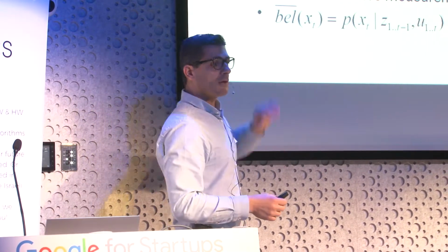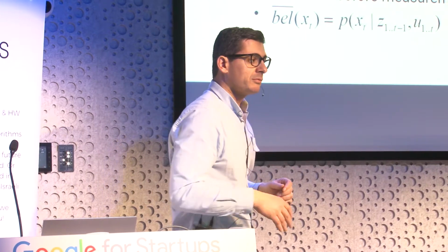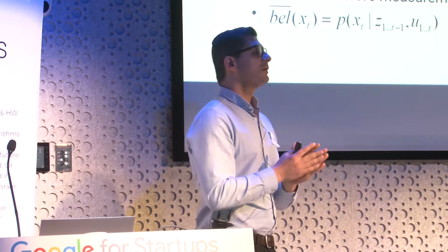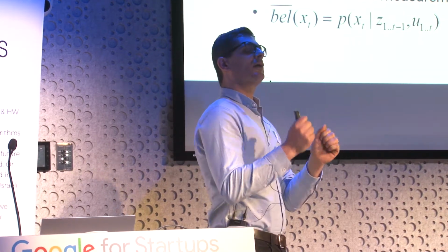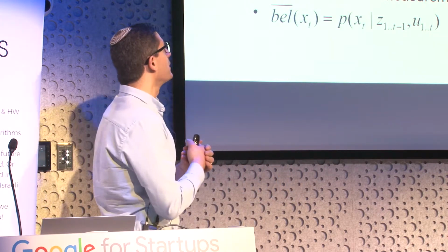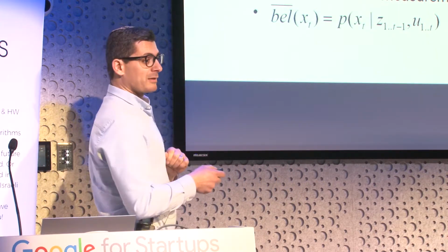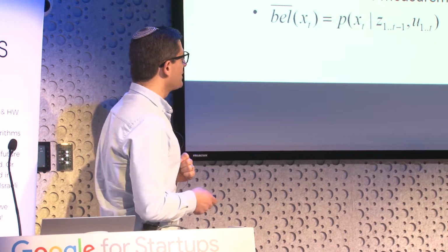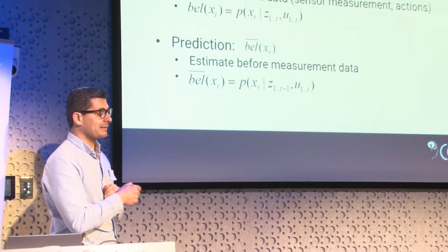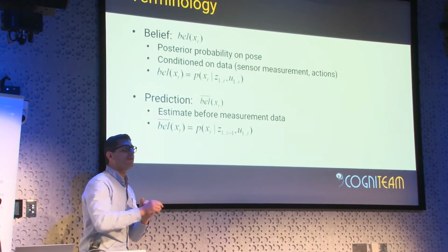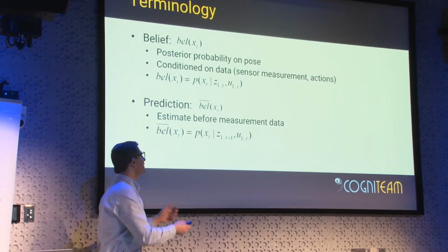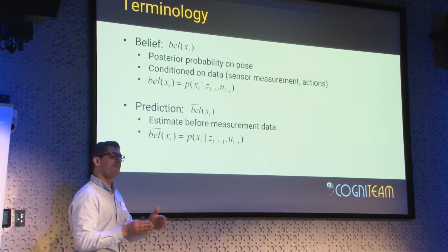And now we'll talk about the belief. Each robot needs to calculate its location. It has its belief, how accurate I am, how sure I am that I'm in the location that I think I am. So the belief bel(xt), the belief that I'm in location xt, means what is the probability to be in xt, given all the sensor readings from the start, and all the movement motion.